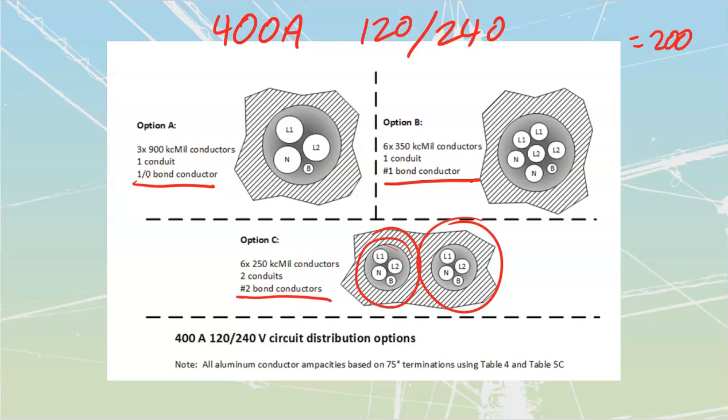Following that inside of your binder, there is a note that says normally the CEC does not permit parallel, and it talks about this exception. That whole top little part of the paragraph over there has now been struck because that has been changed. They changed 12-108 so the rule would now state circuit conductors. A bond is not considered to be a circuit conductor. It's considered to be a safety, but it should not be conducting current. So that is no longer going to be an applicable sub-rule inside there. Don't worry about that one.